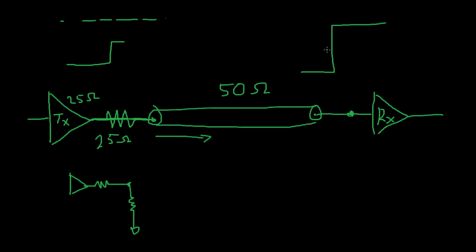There's no stair steps or anything. You don't see much ringing. It's pretty much a perfect signal because it's only got this one reflection going on. You may get a little bit of ringing here due to inductance and other factors. But this is going to bounce back to the other end, and whenever it goes all the way back to the other end, we'll see the other half of our signal show up when that signal reaches the other end, but